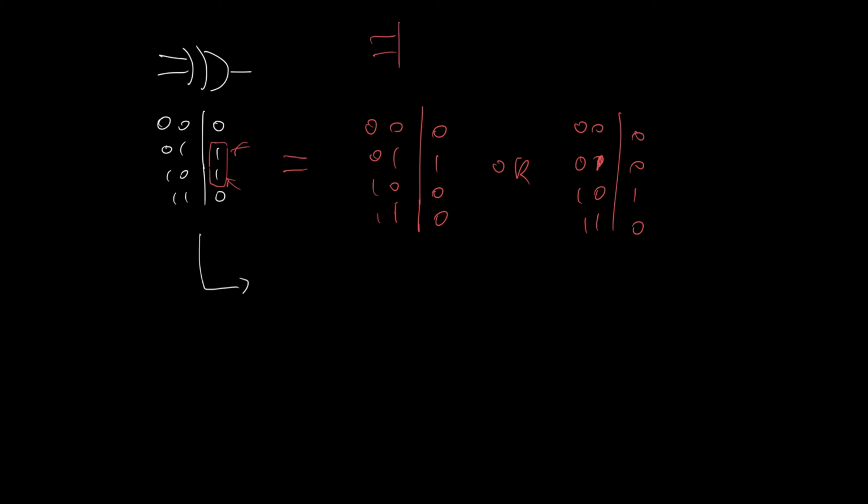And now this last logic gate is my OR gate, and the output of an OR gate is a 1 if either of its inputs is 1. In this case that's not true, so the output must be a 0, and I can write down 0 here. If we now speed it up and take some shortcuts, I encourage you to go through this the slow way like I did for the remaining 3 possible inputs, but the faster way is to do it as follows, and you can do it this way with a bit of experience.